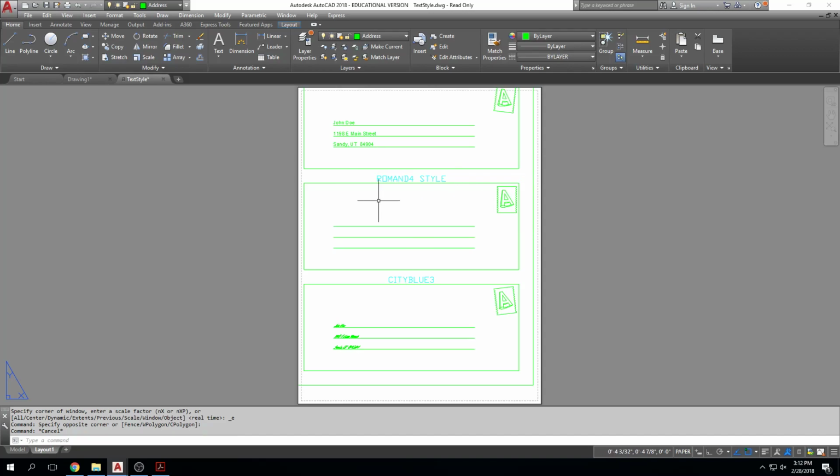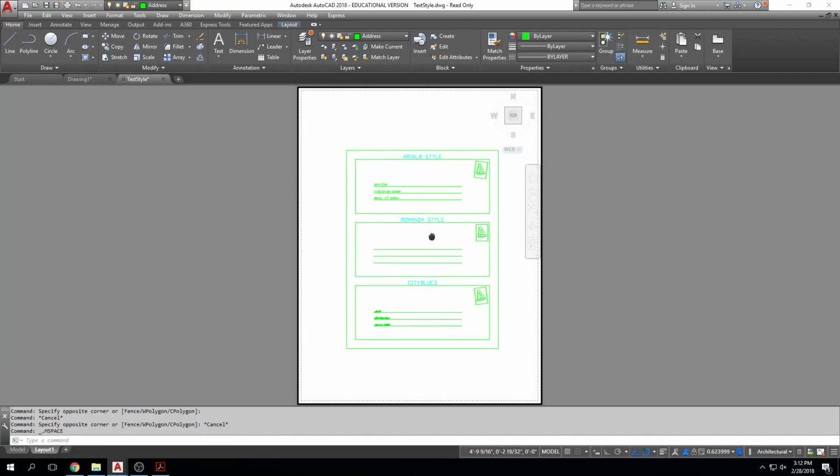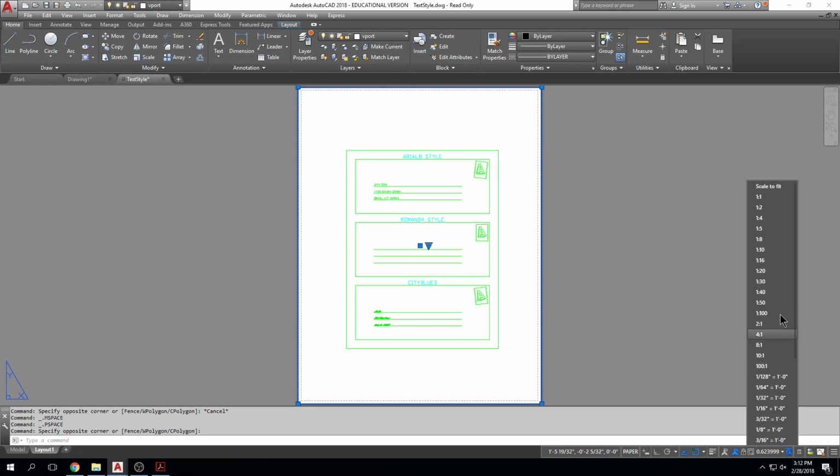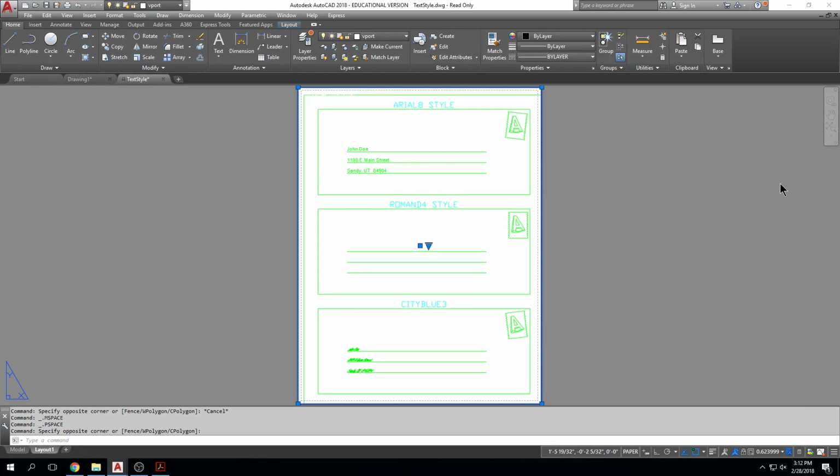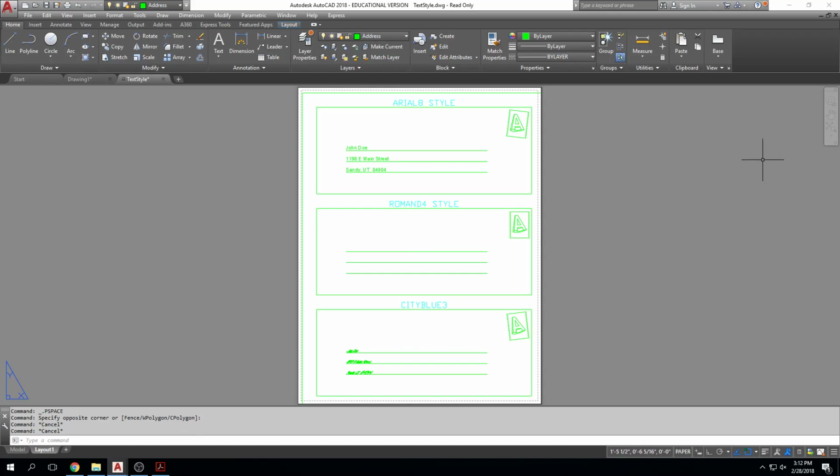Now, I kind of moved the viewport around. I may have engaged the viewport, so I'm not entirely sure this drawing is to scale anymore. And again, we want to make sure these are to scale. It's kind of like the number one most important thing, right? So I'm going to grab my viewport again and just verify the scale is correct. 1:1. Looks really good.